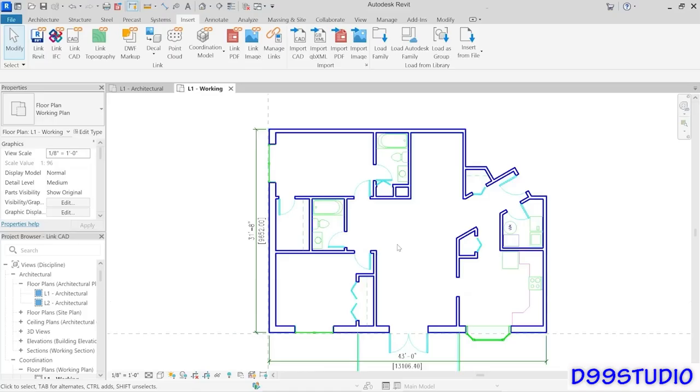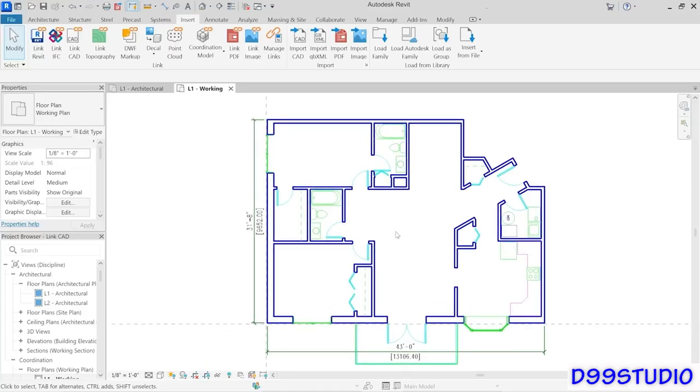So let's say that my designer worked in AutoCAD, and now I want to take their work and I want to start creating Revit geometry from it. Well, sadly, there's no button that's going to convert this CAD file to Revit geometry automatically. So that means I'm simply going to need to trace over this CAD file with Revit walls and doors and other elements. Now, I know at first that sounds a little daunting, but it's actually not that bad.